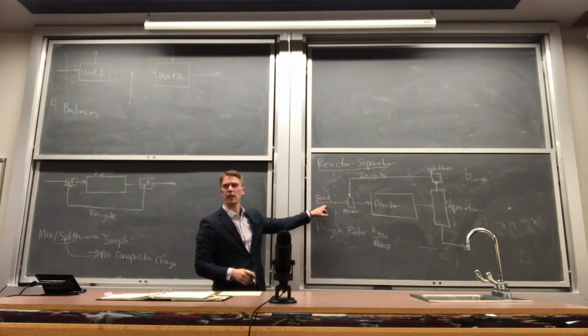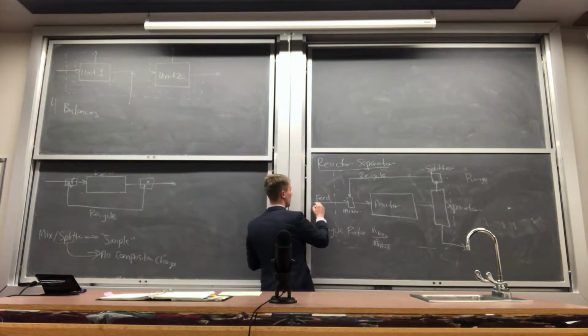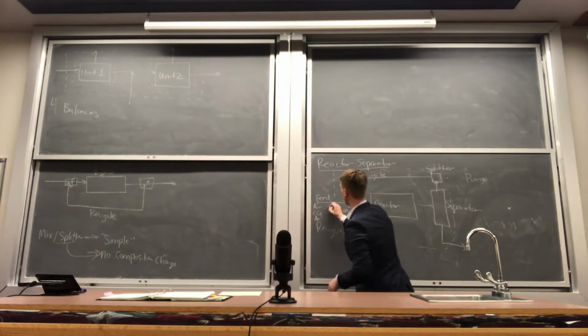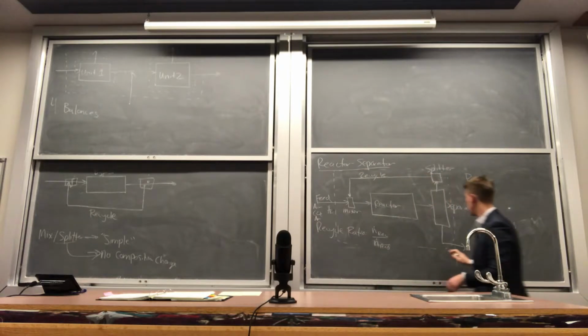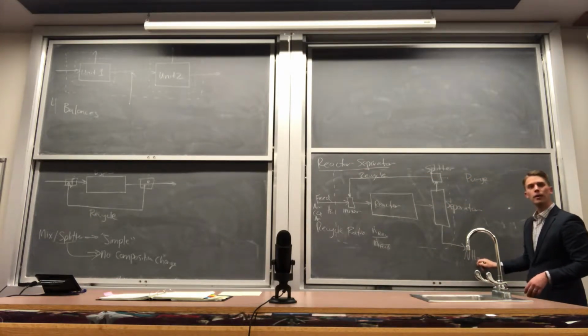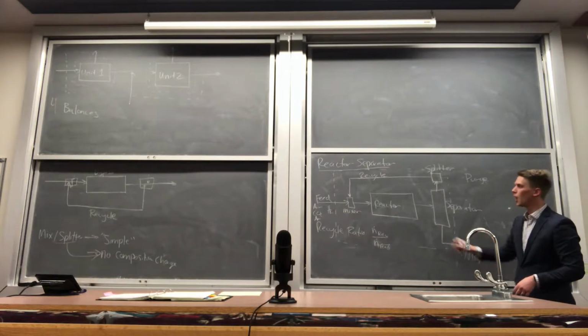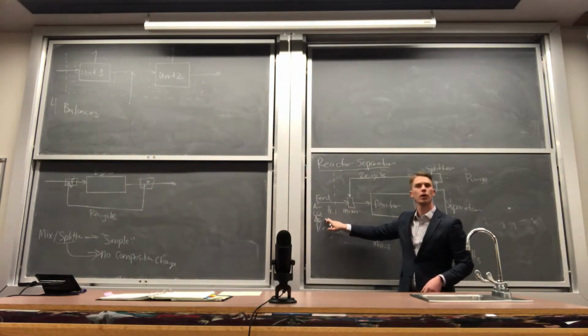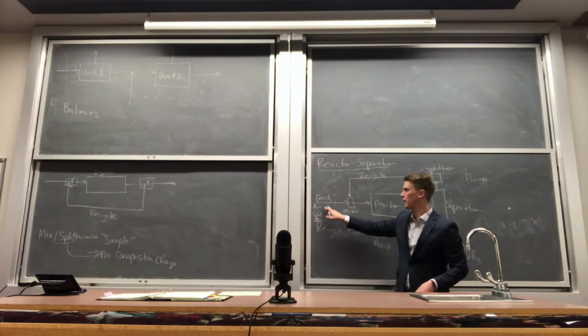If we had a feed that consisted of air, and maybe that comes with a little CO2 and a little argon, and hydrogen, because this is potentially the Haber process, and the product here was, let's say, ammonia, we would have an accumulation of other gases in the system, namely the inerts. CO2, argon, anything else that's not reacting. In this case, the oxygen could also be considered an inert.